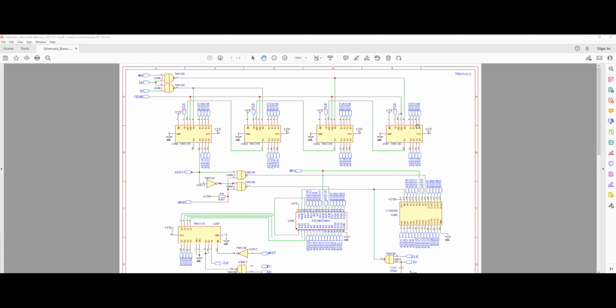As I mentioned, the memory address register has some inputs, and just like our program counter, here we have a high byte and low byte concept, the reason being that our bus is an 8-bit bus. However, our memory address register is a 16-bit register.